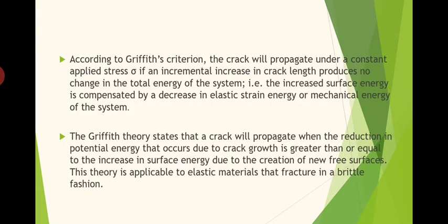Now according to Griffith's criterion, the crack will propagate under a constant applied stress sigma if an incremental increase in crack length produces no change in the total energy of the system.